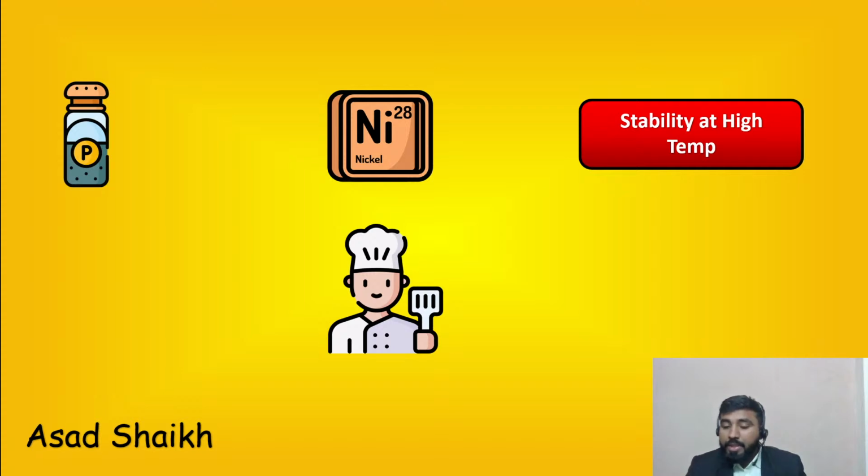Yes, bellow seal valve will then come in. It is the worst case scenario. If nothing works, your fugitive emission is extremely high, which is class A, then only you should think of a bellow seal valve, because it has a lot of maintenance issues, cost is increasing, DP has to be less, a lot of things come into picture.